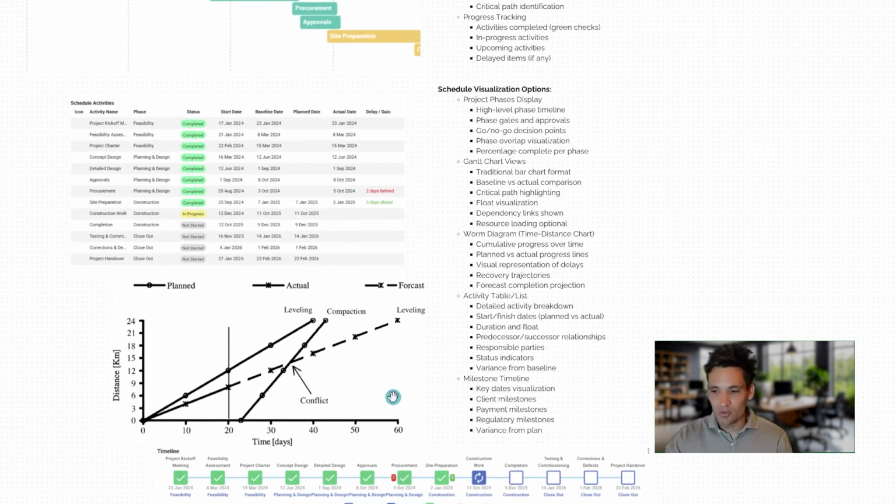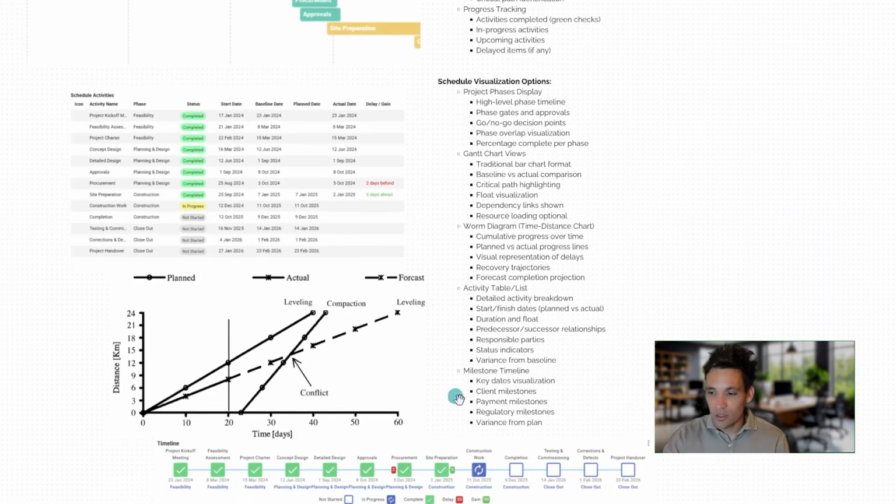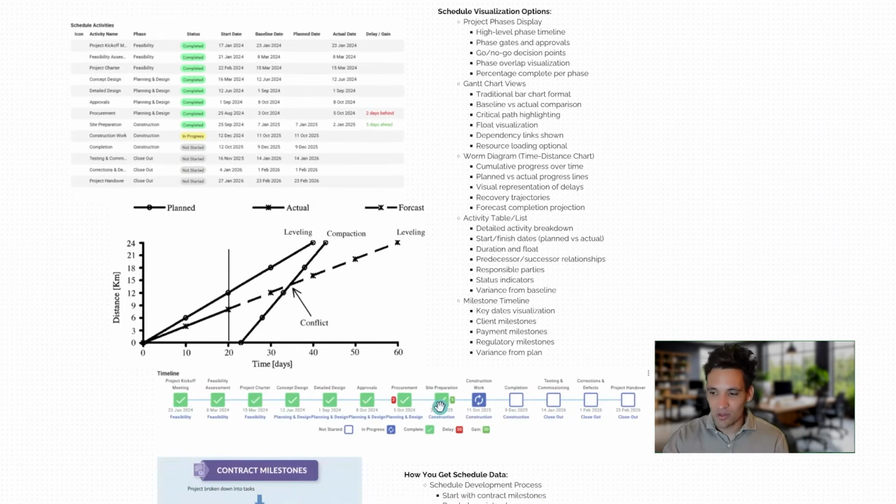For longitudinal projects, so things like road projects, where, for example, you're building a road, you've got set chainage markers, for example, a 24-kilometer road, you can actually map out activities as lines, which gives you a line diagram, which is very easy to understand and quickly see which of the core activities are what's going to delay progress, or you can use something like a simple milestone timeline.